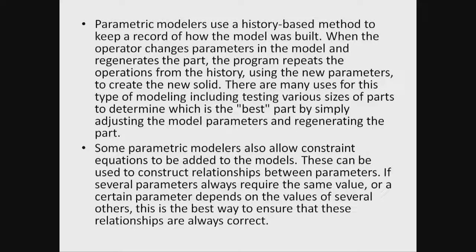If you correctly tie up all these things, and you suddenly find out that you need more space, you can reduce the size of the washer, and things like a counterbore can all be taken care of. Alternatively, if the material, especially plastic, is likely to fail, you can increase the size of the washer and make sure related bushes and all get updated automatically.